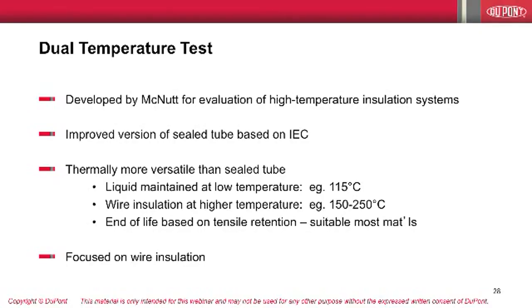The dual temperature test was originally developed by Bill McNutt after retiring from GE as a way to evaluate high temperature insulations in mineral oil. The procedure is an improved version of the sealed tube test that is more versatile, although it is focused only